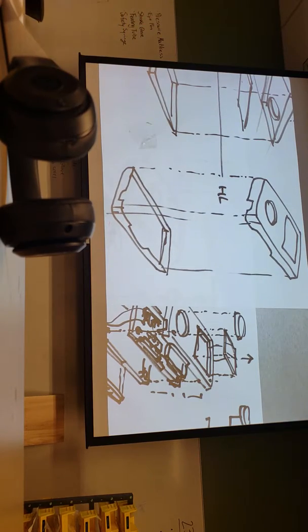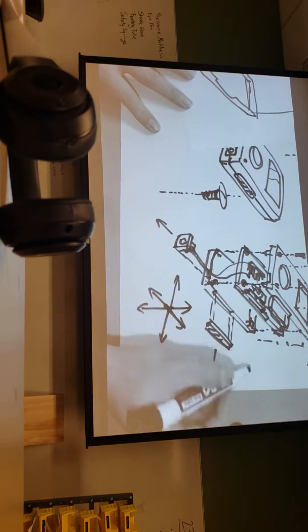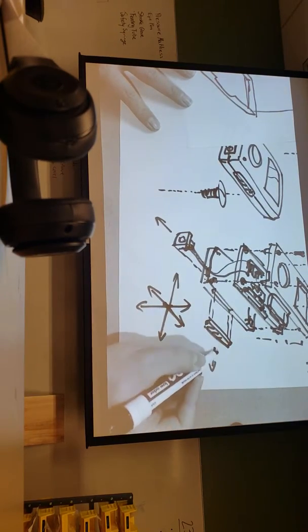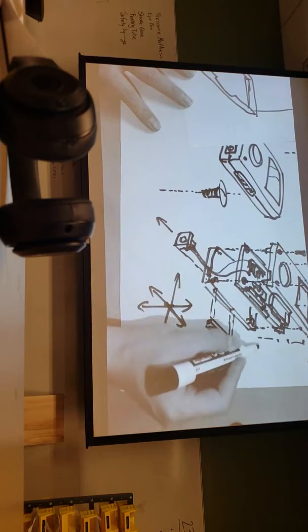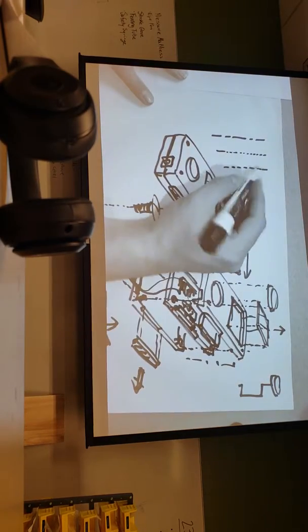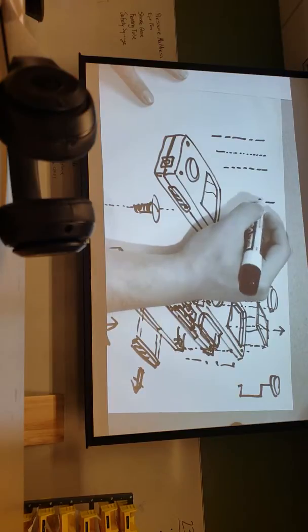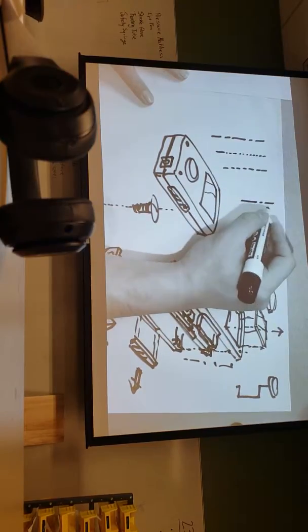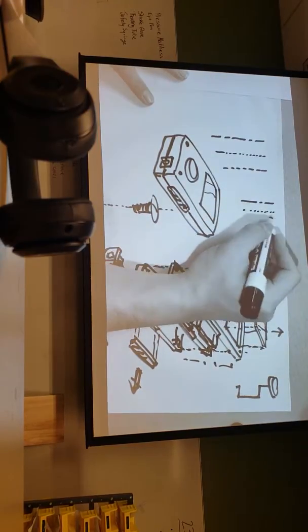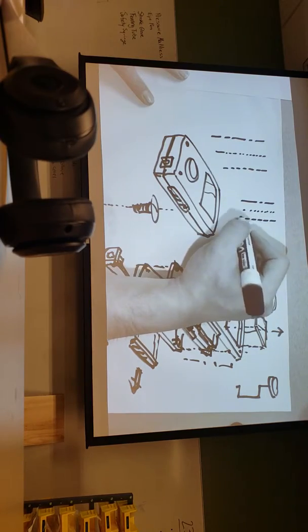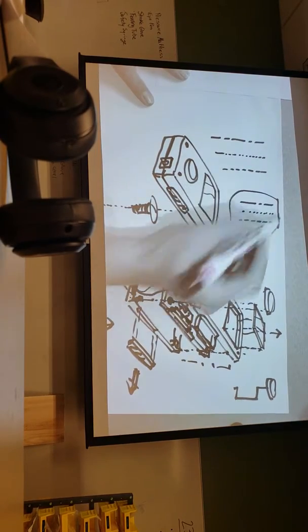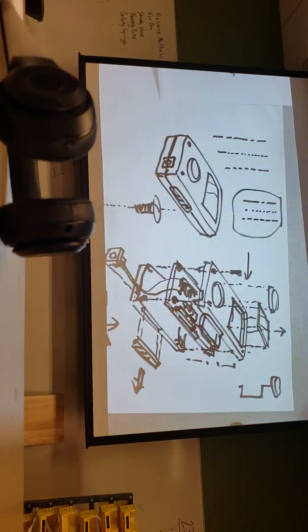So what I was trying to show here is that you have side pieces. Anytime you have something that moves outwards, you can use a combination of arrows and these little dots. These leader lines, I've seen variations in long line, short line, long line, a dot, or little dashes. All of them are done fairly lightly. If you look at the one up on the board there, I think it's just light dashes, but they're very helpful in showing the paths where the parts go together.